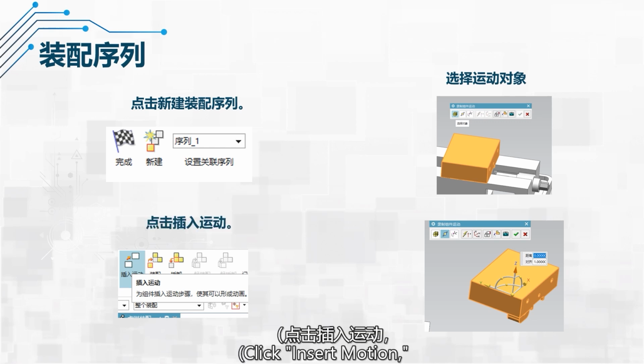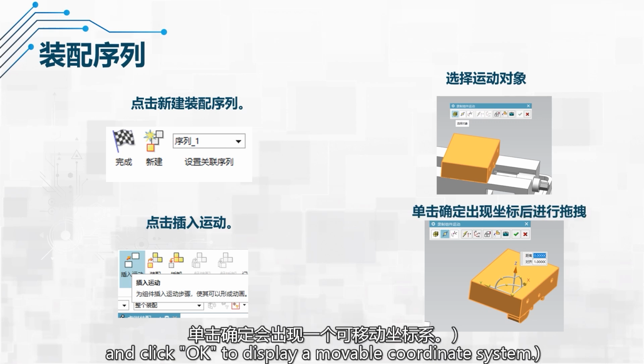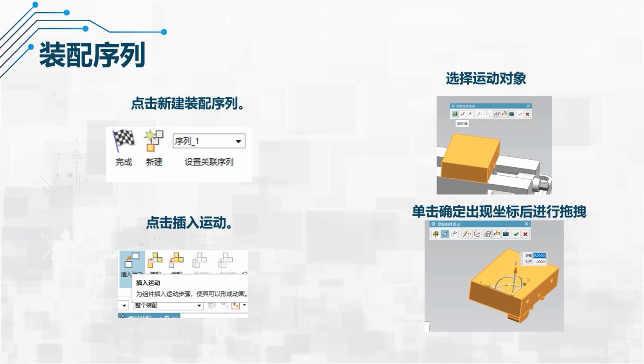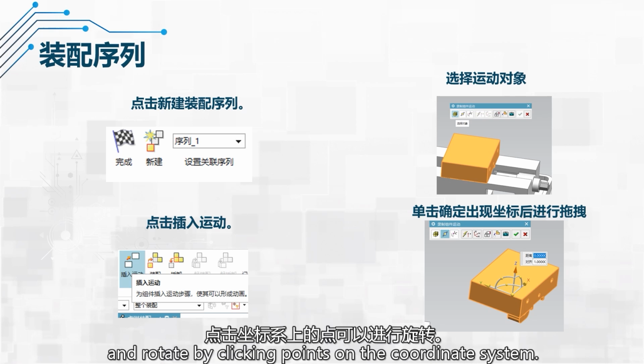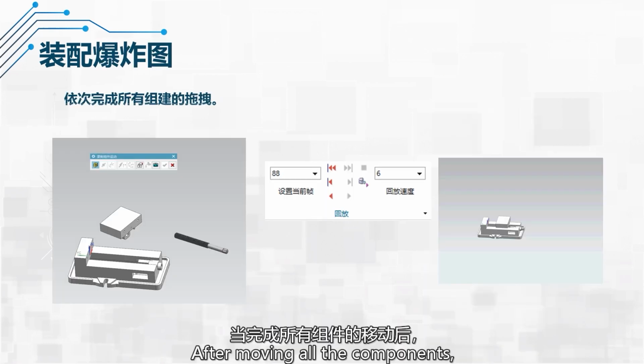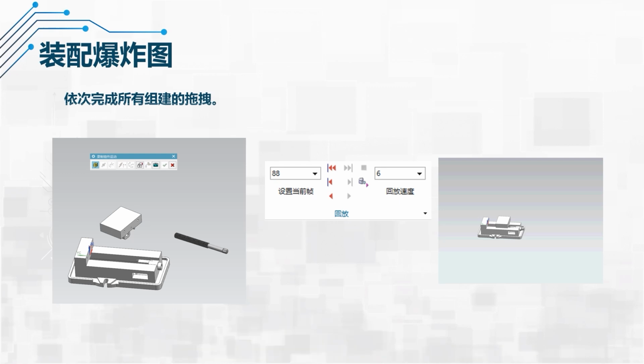Click Insert Motion. Select one component as the motion object and click OK to display a movable coordinate system. You can change the position by clicking the arrows on the coordinate system and rotate by clicking points on the coordinate system. After moving all components, you can go to Playback to set the playback parameters.